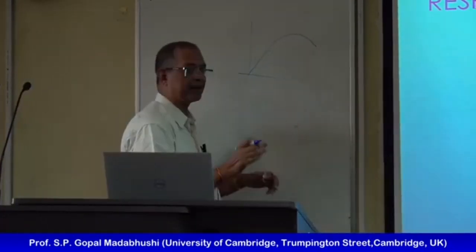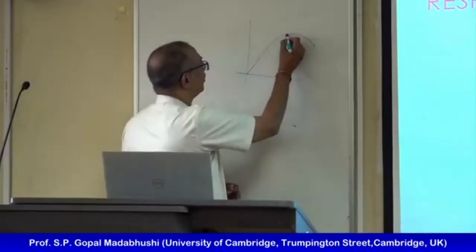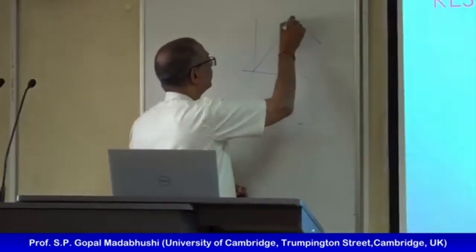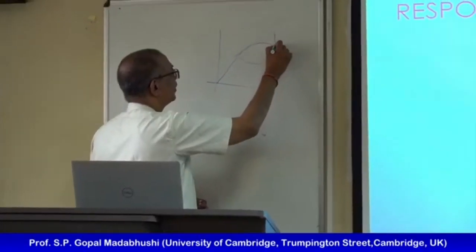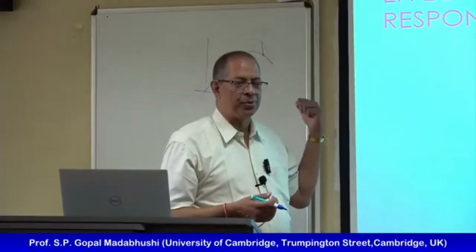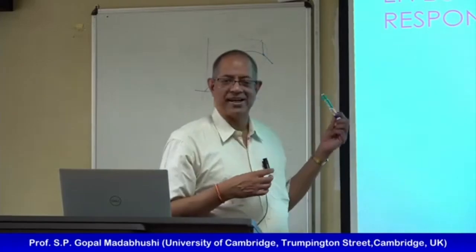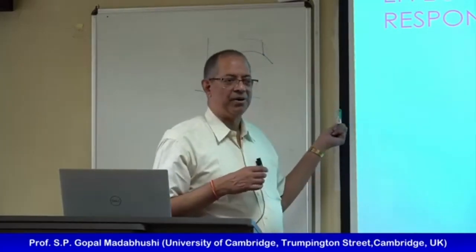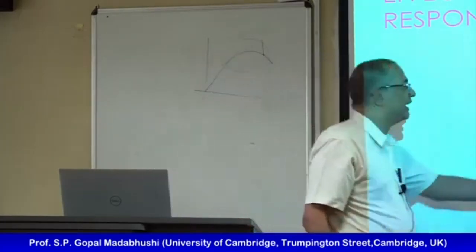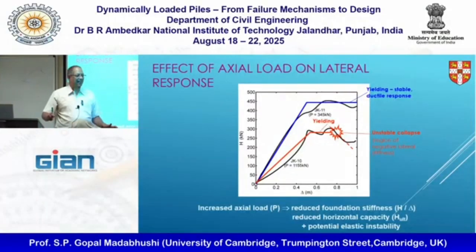If you want to capture that kind of post-buckling behavior, you need to draw a circle around here, draw tangents, and then work your way down, iteration by iteration, and then you can follow the post-buckling deformation behavior of columns. So that's what he has done for the numerical bit, but effectively that is for ego satisfaction. For a practical engineer, once you reach this, as he has drawn here, crash bang, pile dead is about right.